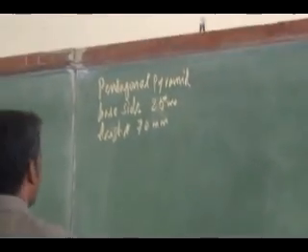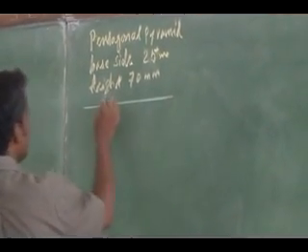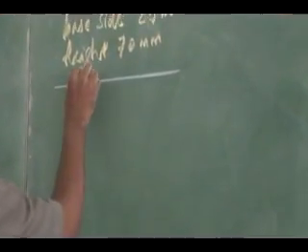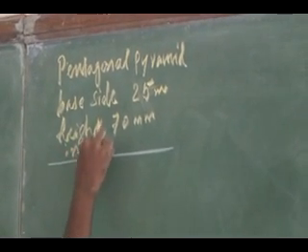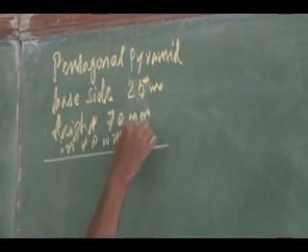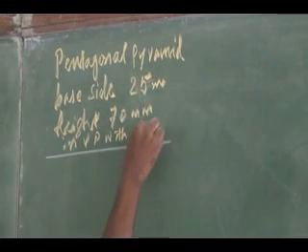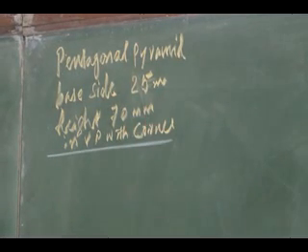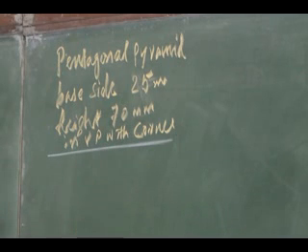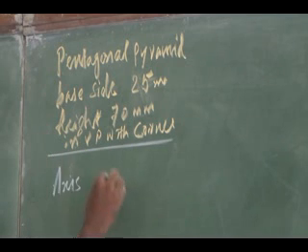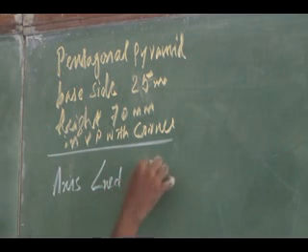So in this orientation, I know the hidden data is: it is in VP with a corner, and the slant edge containing that corner is perpendicular to VP, and the axis is inclined to VP.